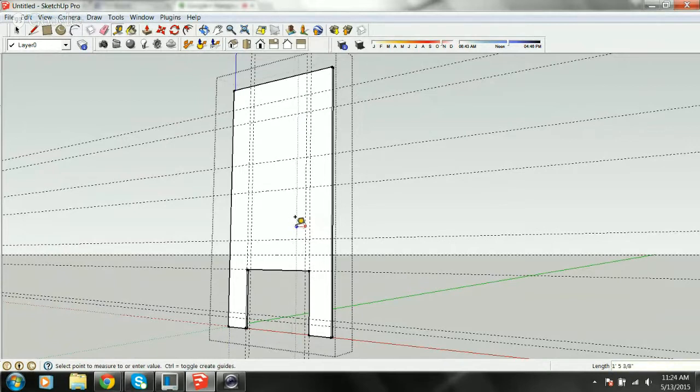Okay. Now you see how, remember before I tried to grab that dashed line and it didn't do it? It wouldn't offset? Well, now this side's going to do it. Okay, so now I'm in 8 inches right here, and I'm going to offset this. I've determined these windows are approximately 3 foot by 6 foot 8. So 36, 36, boom. Now I've got this opening here and this opening here that form the 2 windows on the second floor, because we know this is that headline that we created with our earlier step. So again, rectangle, come up here, push, pull.